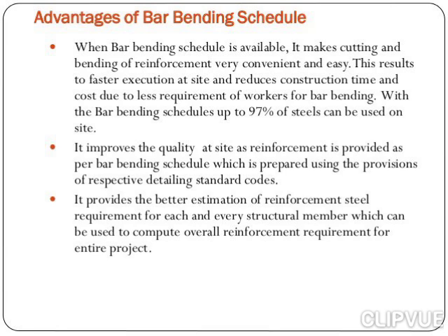Advantages of bar bending schedule. When bar bending schedule is available, it makes cutting and bending of reinforcement very convenient and easy to use. This results in faster execution at site and reduces construction time and cost due to less requirement of workers for bar bending. With the bar bending schedules, up to 97% of steels can be used on site.